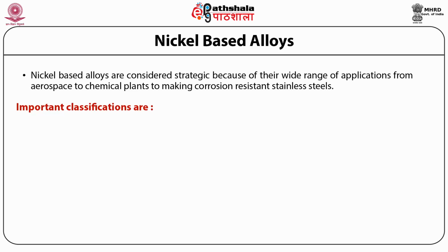Nickel and its alloys are classified into several groups. Commercially pure nickel has good mechanical properties and retains its strength at elevated temperature. It has also excellent resistance to most corrosive environments. It is used in making food processing equipment, electrical and electronic parts, caustic handling equipment, etc.